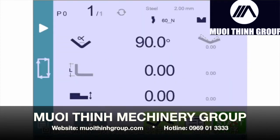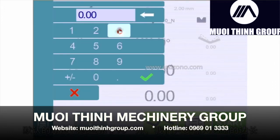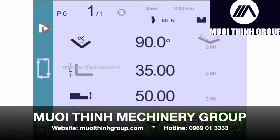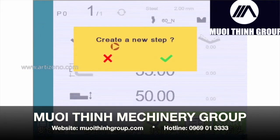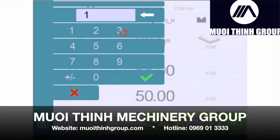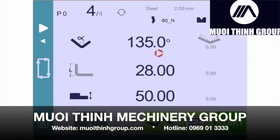Coming back to the main page, we will now program the first bend of our part. If you remember the drawing, it was a 35mm long flange with a 90-degree angle. The default angle already shows 90 degrees. We will then just program 35mm for the flange's length. To create the following bend, we just need to touch this arrow. The next steps of our program are made in the very same manner, and we'll quickly breeze through them.